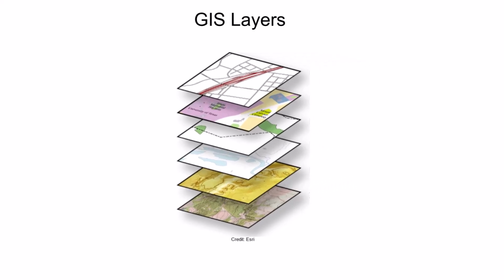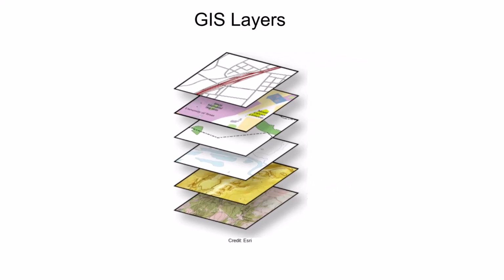For instance, in an urban planning project, a transportation layer shows roads, railways, and transit routes. Other layers could represent population density, land use, or the location of residential, industrial, and educational facilities. A utility layer might display water, waste, and power lines. Physical layers might include topography and flood zones. Together, these layers form a detailed model of the real world.